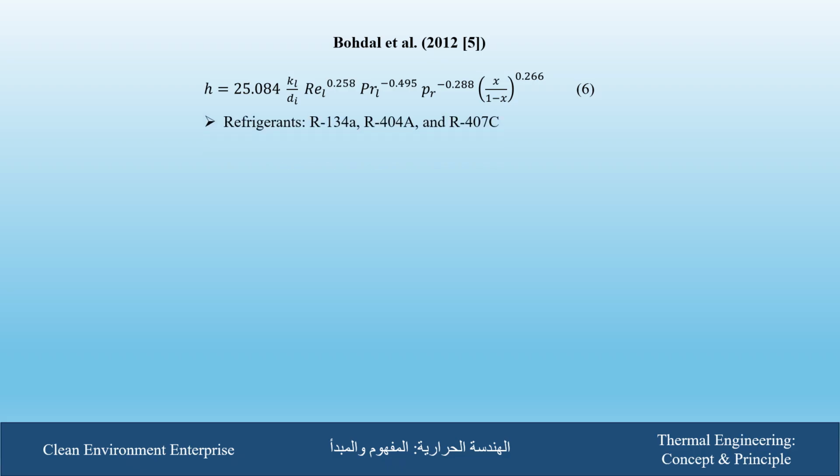This equation was obtained for refrigerants R134A, R404A, and R407C, which is a zeotropic mixture with a little temperature glide between the dew and the bubble temperature.